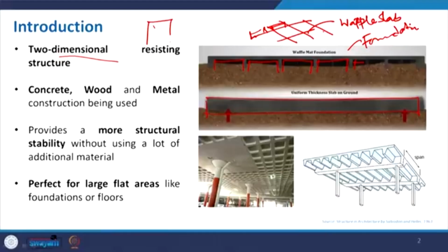In one particular discussion, when we discussed the efficiency of a structural form, we saw that whenever we take a solid rectangular section, the maximum bending stress occurs in the outer fiber, whereas at the center there is a lesser amount of stress. For that we can improve it, we can make this an I section.